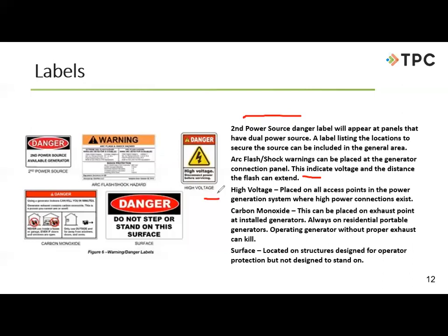Definitely want to have something on there to indicate to us that this is a higher voltage than 50 volts, right? And that there could be a shock hazard involved. We would definitely want to know the exact voltage on that label, and that is just a pet peeve of mine. If we're going to tell people that they're qualified, then my number one top criteria is they have to know the voltage. And I don't care what we're dealing with, they're going to have to know that.